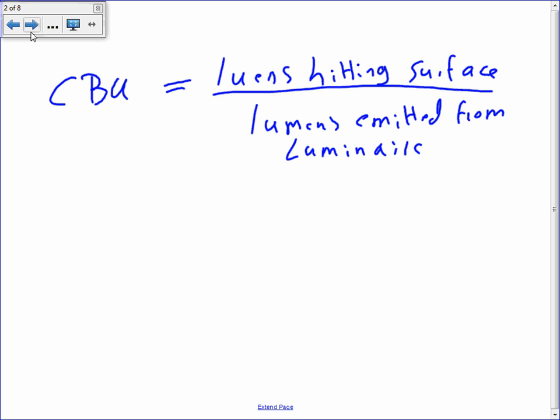If I go up or down, that factor will be worse. Does that make sense? It's the factor that gets you the best performance of the fixture. They define it as how many lumens got out of the fixture versus how many lumens hit Brian's head as I point that light at his head when he's playing football or any other game. Okay? So that's just a definition.